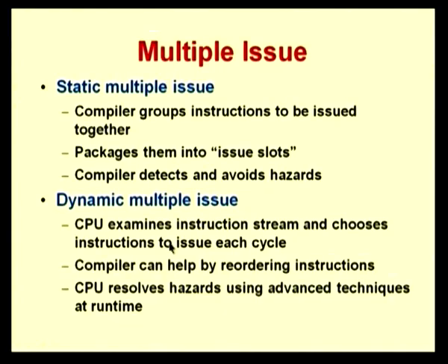Now coming to dynamic multiple issue. What do we expect in dynamic multiple issue architectures? Here the CPU, that is the hardware, will examine the instruction stream and choose the instructions which can issue in a given clock cycle. Of course, you can have some help from the compiler by reordering the instructions, but it is the job of the CPU to resolve hazards at runtime. We will look at some of the techniques that are used by the CPU to do this.